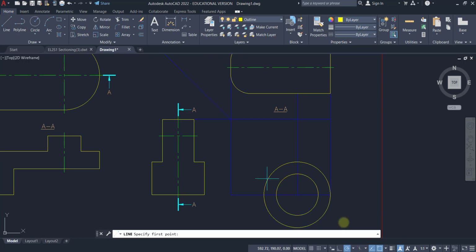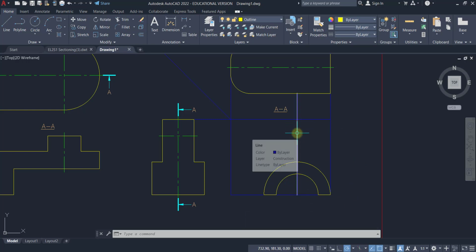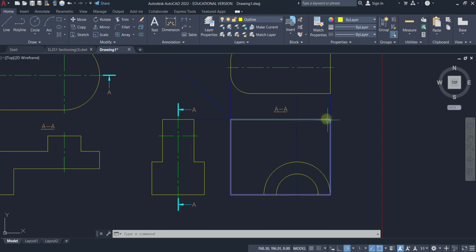Okay, next just draw a line. Repeat by pressing spacebar. Done, just press spacebar or enter. Trim away the bottom half of the semicircle. Escape. Now I'd like to draw the tower portion. I notice that the center line is where the tower is. And I also know that the radius of 19 will be somewhere here.